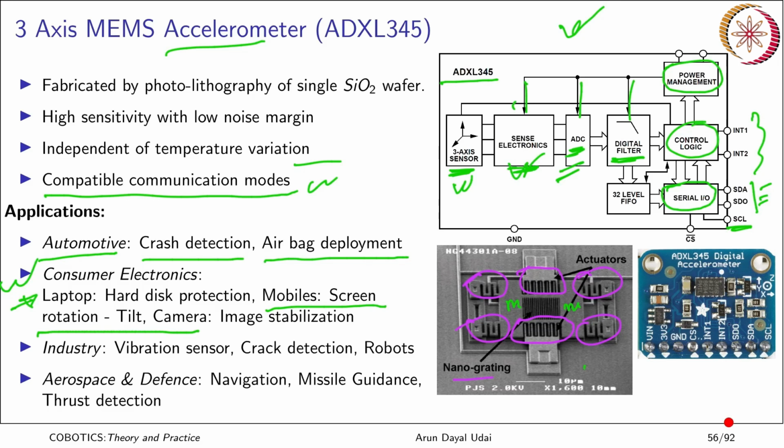Based on the components of G along all 3 directions X, Y, Z, you can estimate the tilt also. So Gx, Gy, Gz are sensed by 3 orthogonal accelerometers, picked up and converted to tilt, and that becomes a tilt sensor.